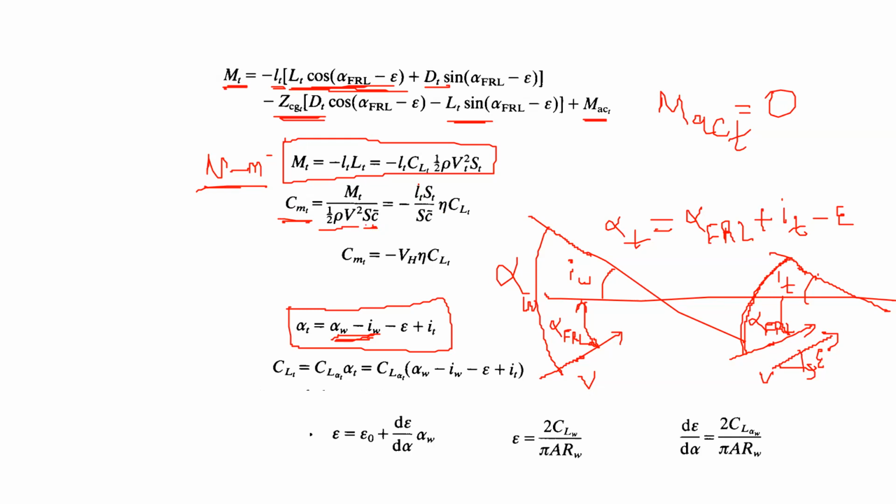Now a ratio appears, because LT and ST are sitting right there, and you non-dimensionalize with the dynamic pressure experienced by the wing, with the wing area and the mean aerodynamic chord of the wing. So we are dividing by the numbers experienced by the wing. Remember that during the non-dimensionalization.